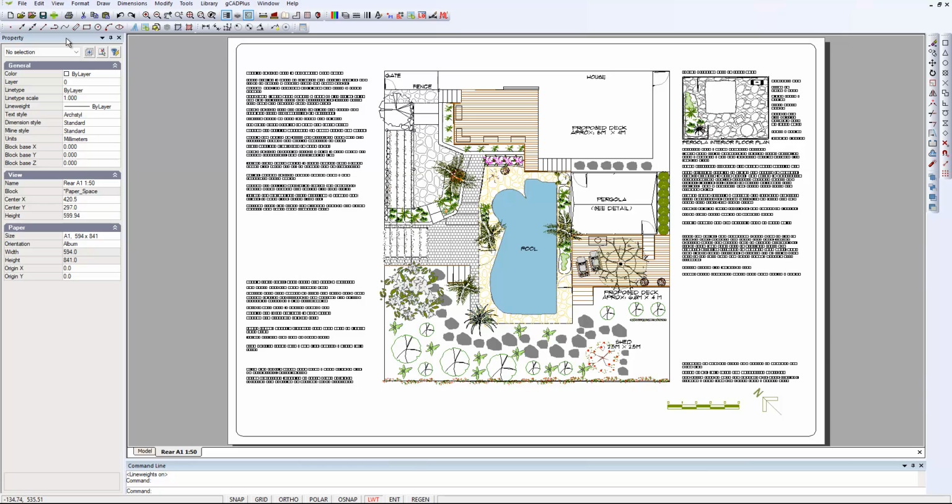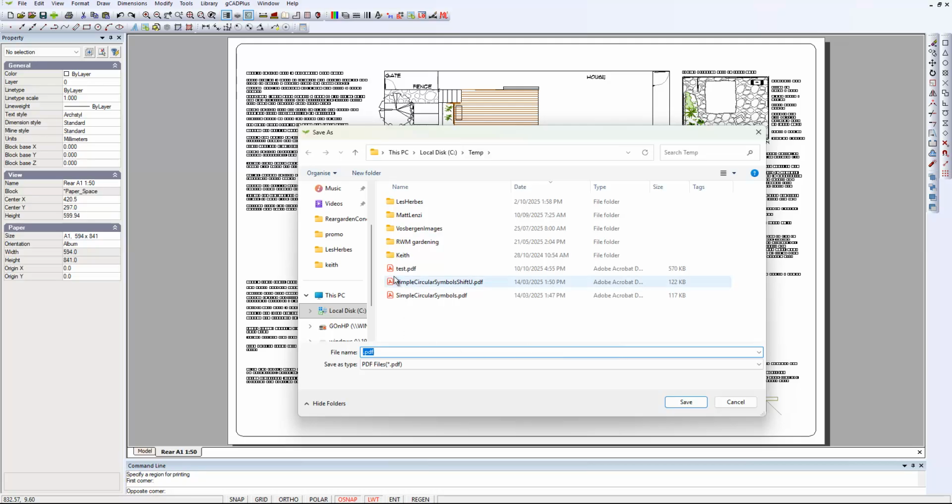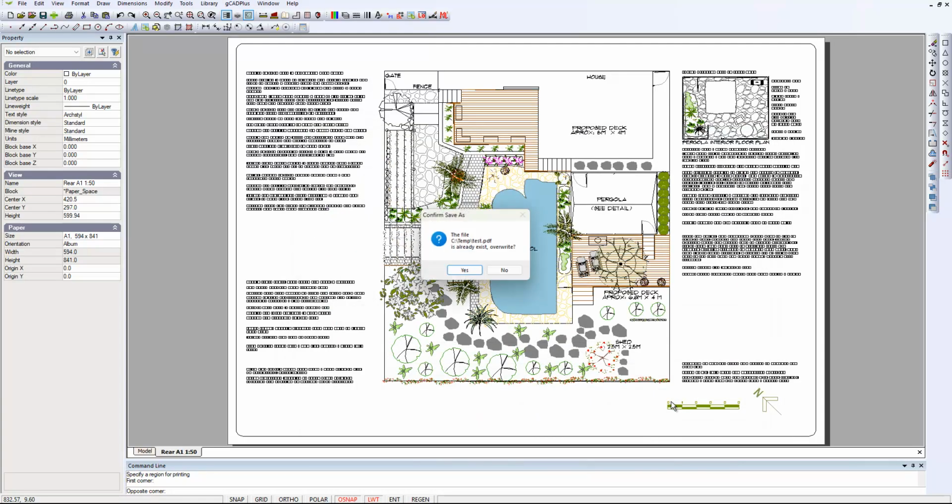no we don't, we want to go File and Save as PDF because it's much quicker. We'll plot in a window at high resolution. Just as a quick check, we could go to maximum later, but that will do nicely. First corner, we'll go outside of the border of the design and in, and we'll just do a test one. I've already made one, so we'll overwrite it.